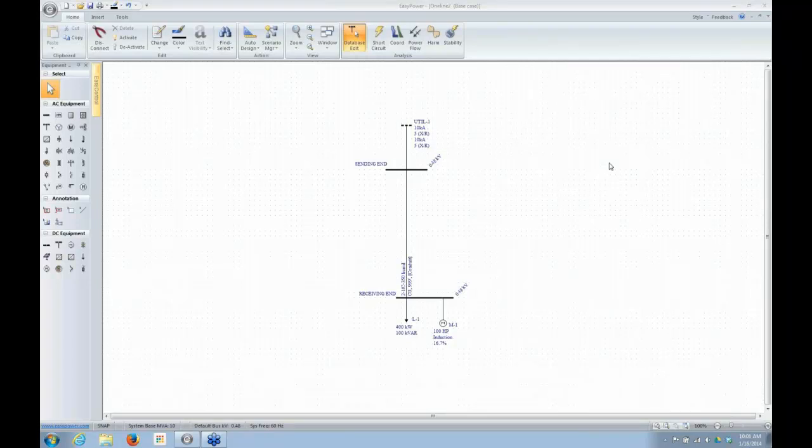So when we talk about the load, we have to refer to whether we're talking about the actual load that we would see if we were to meter it, or the load that we calculate to size our cables, breakers and buses per the National Electrical Code.